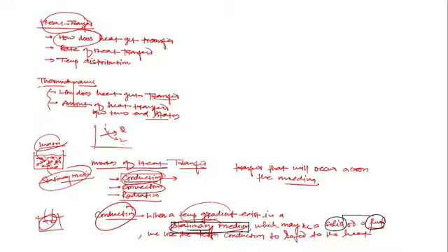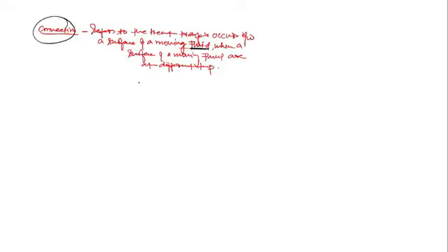Clear, beta? So conduction is possible in the solid as well as in the fluid. If I am talking about conduction in a fluid, the medium must be stationary. As far as convection is concerned, the fluid is a moving fluid, and it is only in the fluid, not in the solid. Convection can never be possible in a solid, because convection refers to heat transfer between a surface and a moving fluid, when the surface and the moving fluid are at different temperatures. Clear?